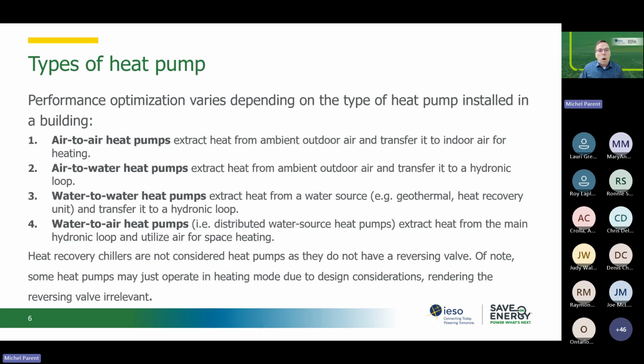You get the air-to-water heat pumps. Again, it's using the air as its source. And that's always very important, because as soon as you've got an air source heat pump, you know you will very often be limited in terms of how that heat pump can work under colder temperatures.